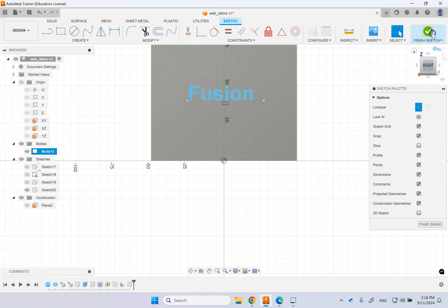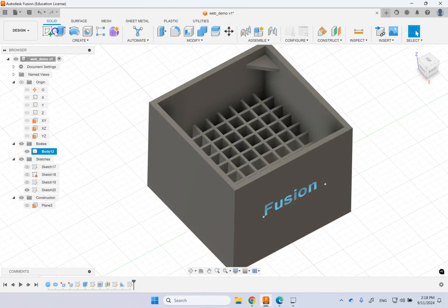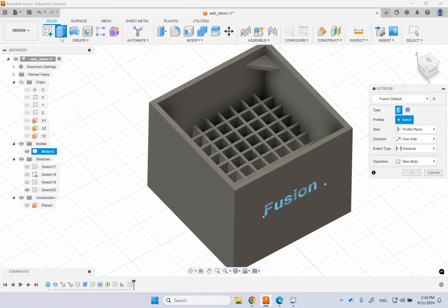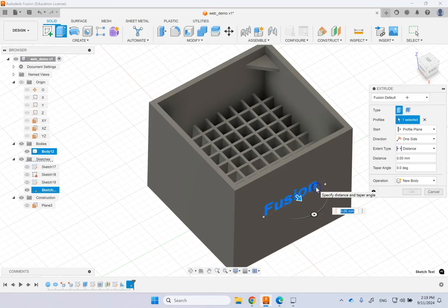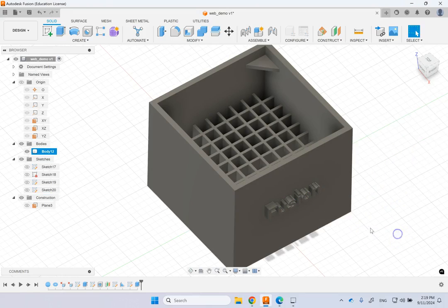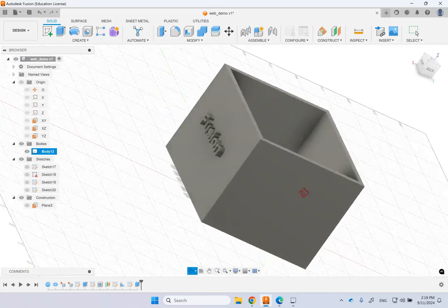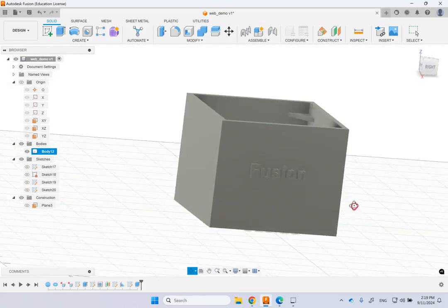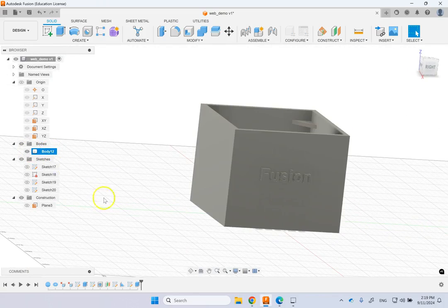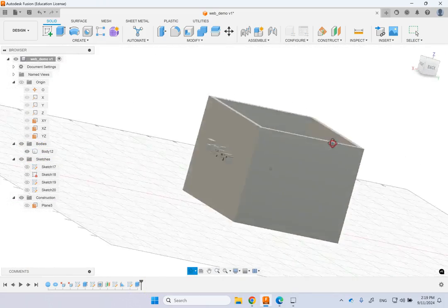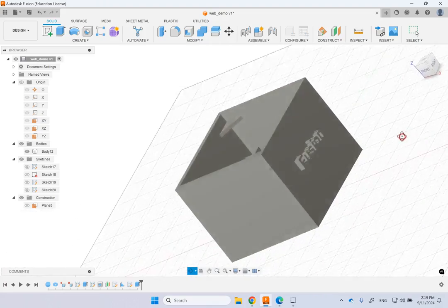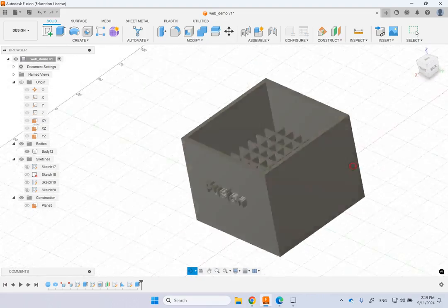And if I get out, now I should be able to extrude this one. So if I pick this sketch and give it some depth like that, look, you see, it's joined the previous one, so they become one object. As you can see, there is only one body here, but this is that extrusion of that. So that's not really what emboss and deboss can do, because doing it on flat surfaces is easy.